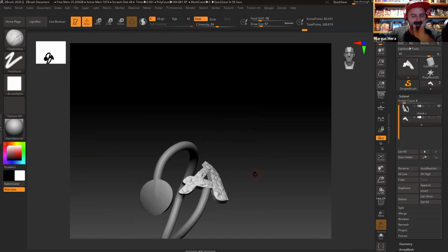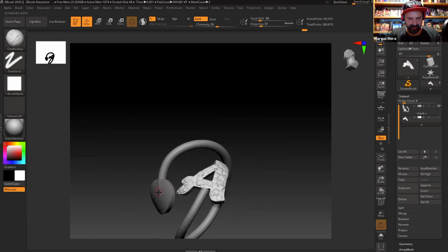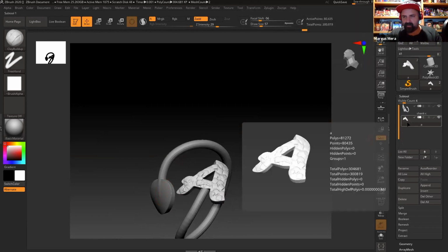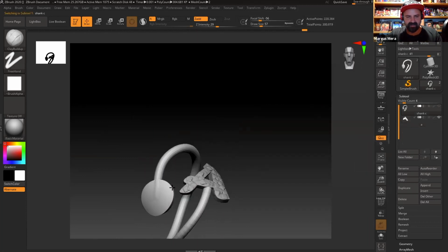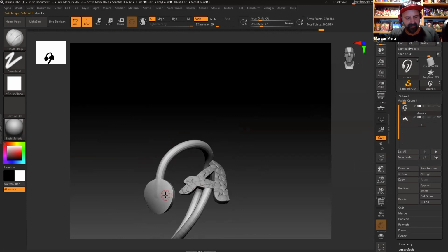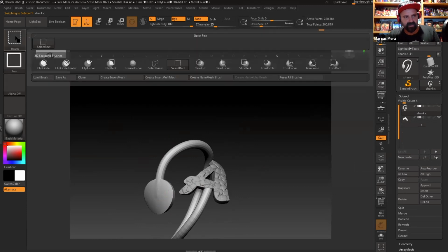If I want to put diamonds, all right, yeah, we could still do the diamonds, but you know what? Let me actually get rid of this circle here. And there's a reason for it. I'm going to want to pave the other material. So in order to do that, let's just delete this. So I'm going to go Control Shift Alt, left click on that box that's up here in the top left and switch to select lasso.